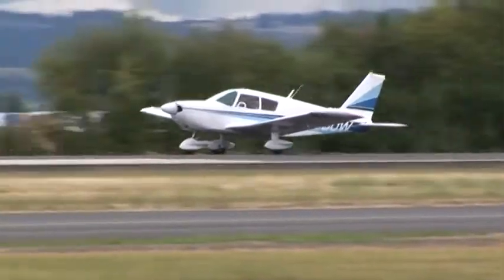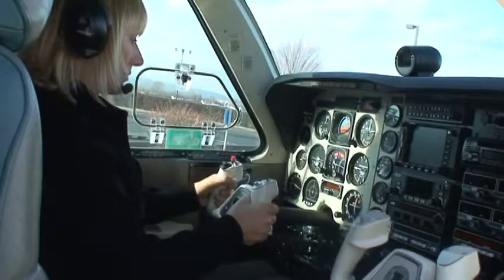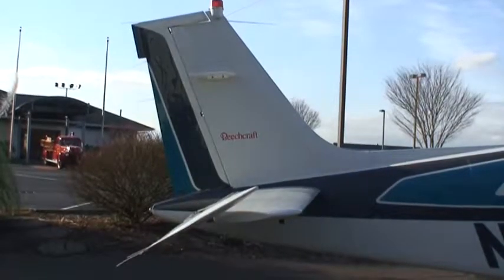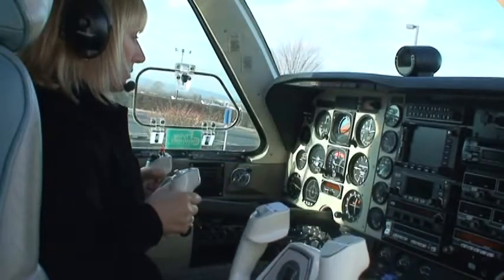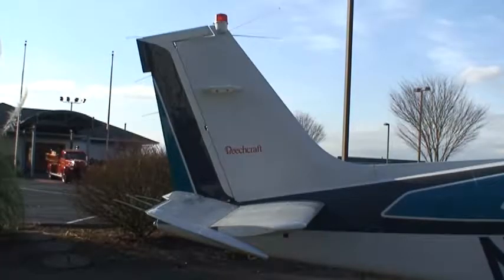And when the pilot pushes the control wheel forward, the elevator pivots down like you see right here, and the tail is forced up, causing the airplane nose to pitch down. That nose down pitching causes the airplane to descend. Now, just the opposite occurs if you pull back on the control column. The elevator moves up, forcing the tail down, and the airplane climbs.